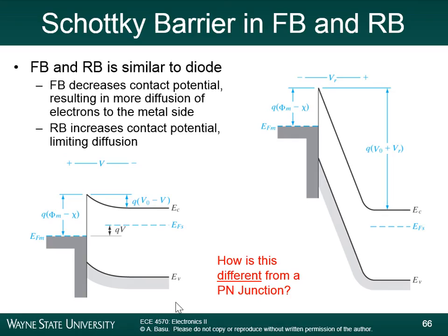Going to the valence band? Yep, from the metal. Okay, from the metal to the valence band. Remember the valence band is mostly full because there aren't that many empty states there. So these are all full. Because everything's full, there's no room for carriers to move around. So most of the interesting things are happening up here.